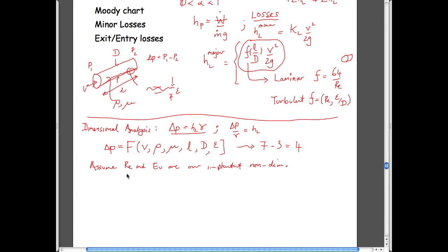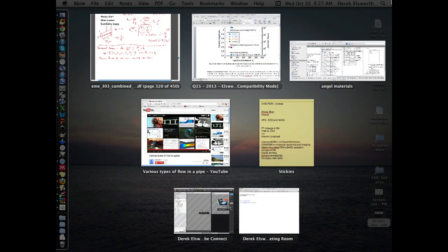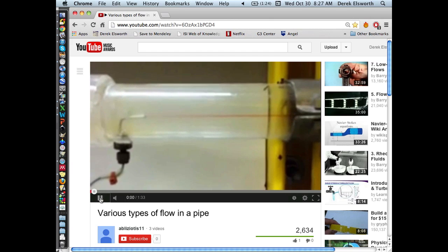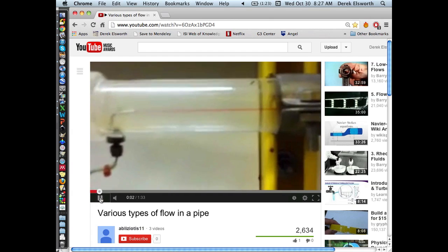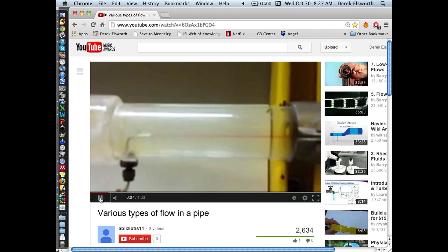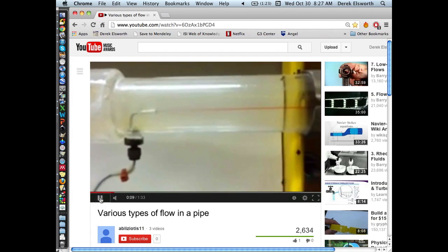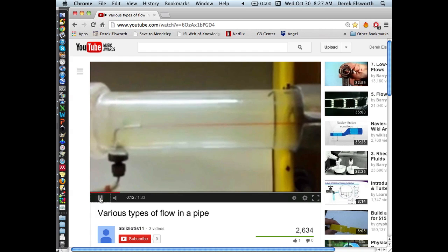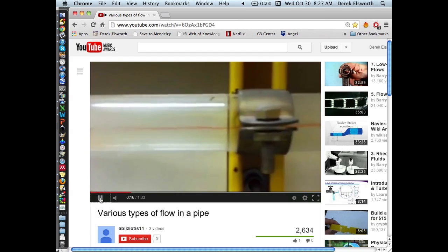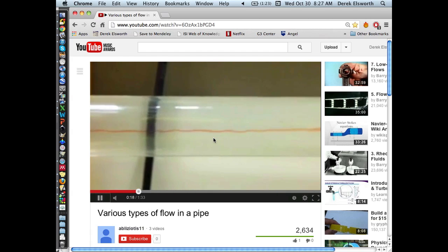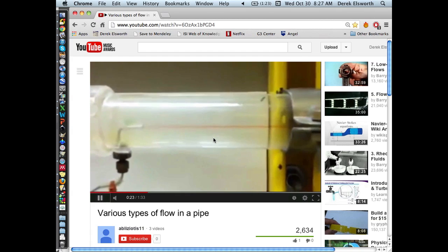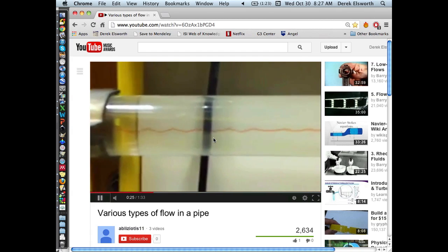Well, Reynolds number is important, right? Because what Reynolds number does is it conditions the flow regime that we have. If we think that we're using our glass tube and we want Reynolds number similitude to be able to calculate the Euler number, then we know that as you change the Reynolds number in pipes, there is some significant change in the flow regime, and so that might be an important indicator that we have to look for in terms of similitude.